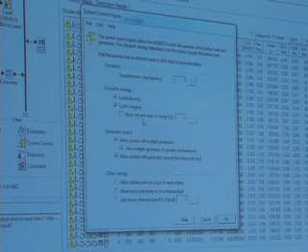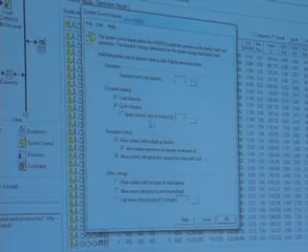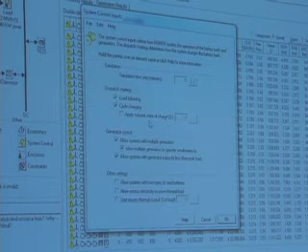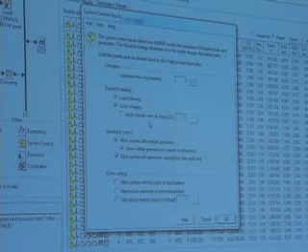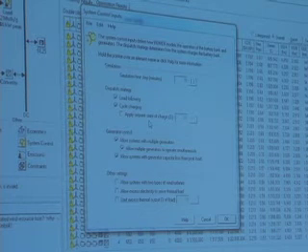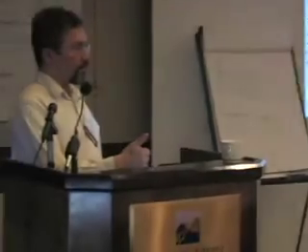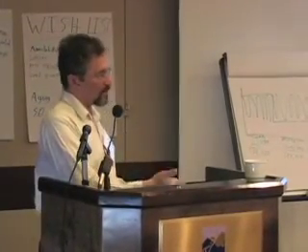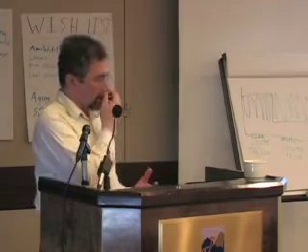Now, if you do cycle charging, the set point state of charge probably deserves some discussion because it's not intuitive what that means. There's all different kinds of set points. So let me explain what this means. So with cycle charging, Homer would prefer to meet the load with the batteries than with the diesel because the diesel is incurring fuel costs. But if the batteries can't meet the load, it turns on the diesels.